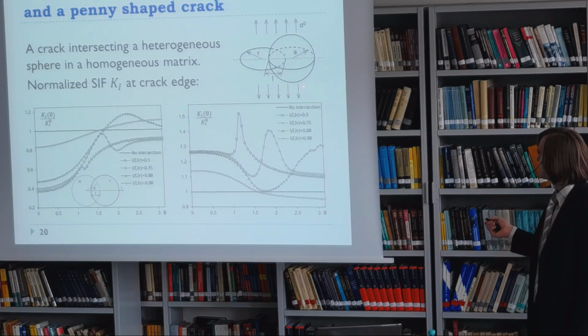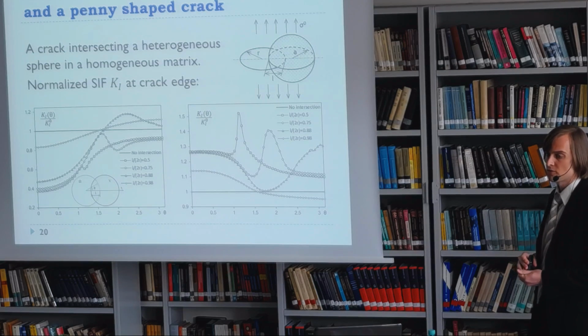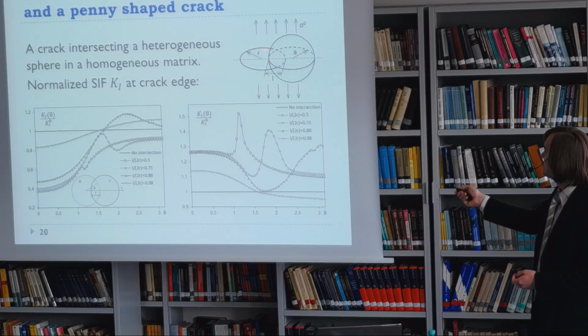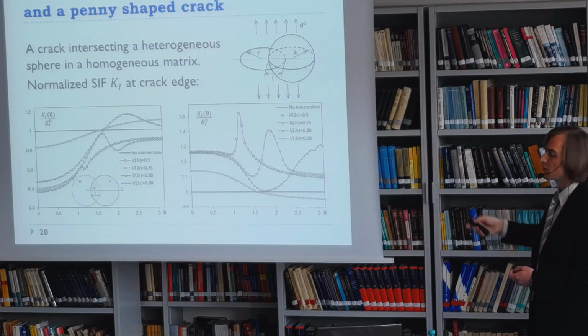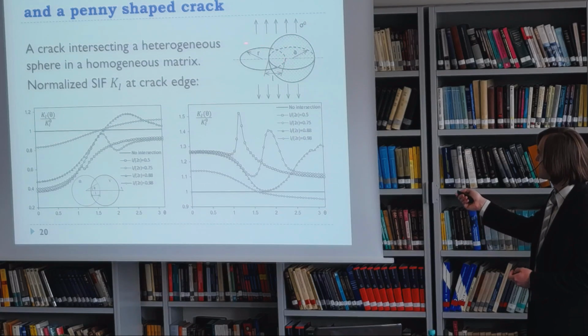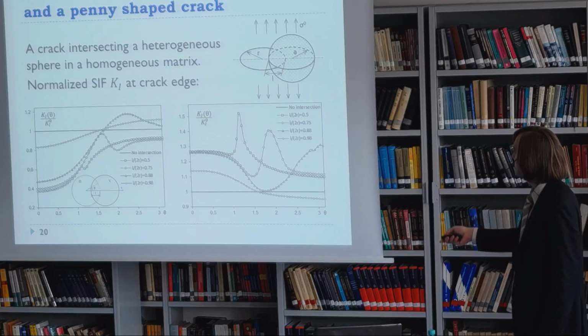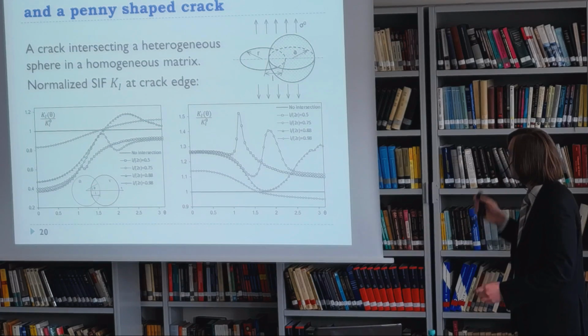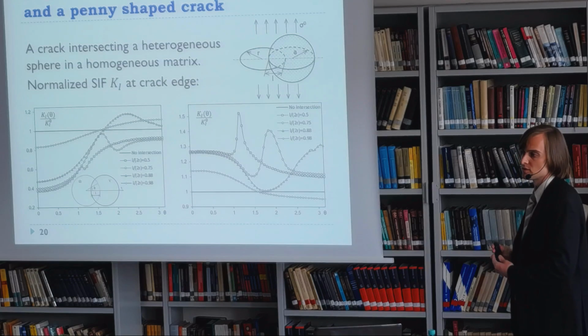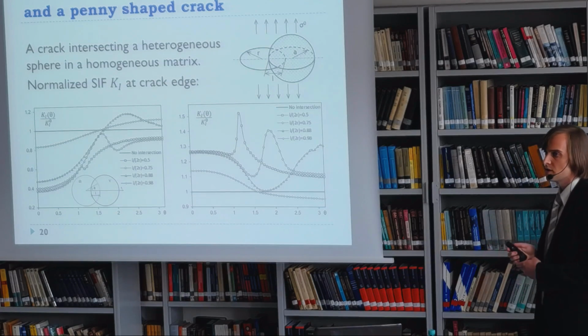And we have applied it to a previously unsolved problem. Actually, I haven't seen any solution of a problem of a crack intersecting with a spherical inclusion. We have also solved it, and calculated the stress intensity factor on this penny-shaped crack edge. Here it is, the stress intensity factor. So it was a previously unsolved problem, in order to prove the flexibility of the method, that it might be applied to unsolved problems as well.